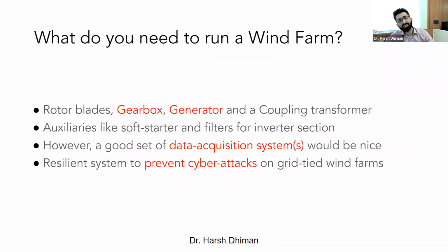So you are looking for an instrumentation system where you can get multiple data. High frequency data is sometimes desirable because you are looking at a gearbox operation which is continuously under stress from the incoming wind speed, and then there is a coupling involved. So yes, that's what you need to run a wind farm.